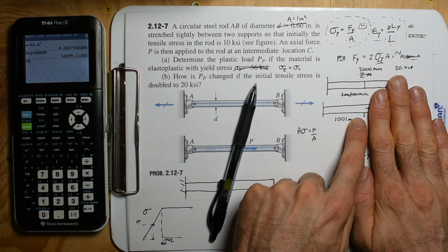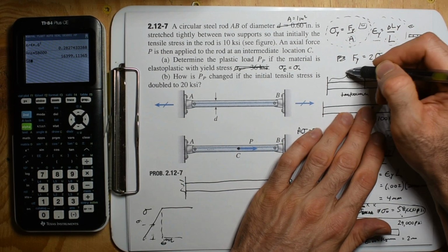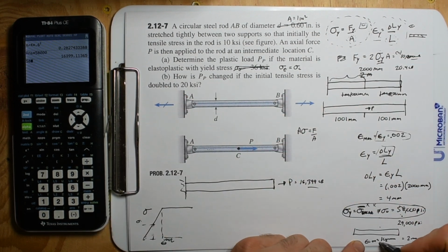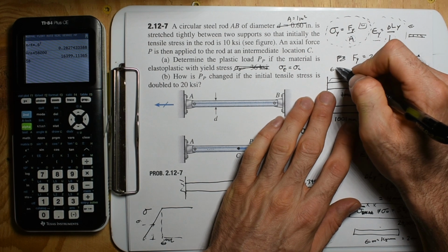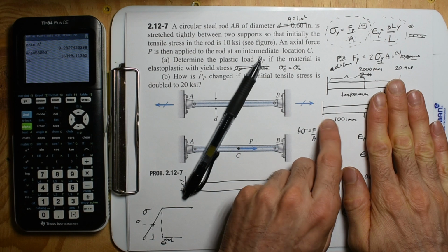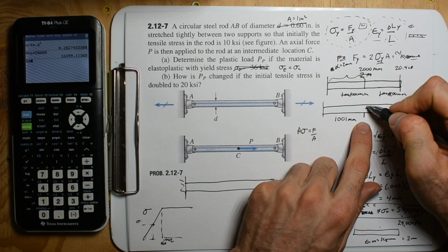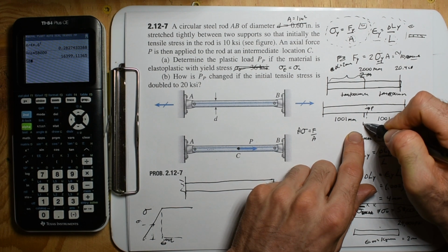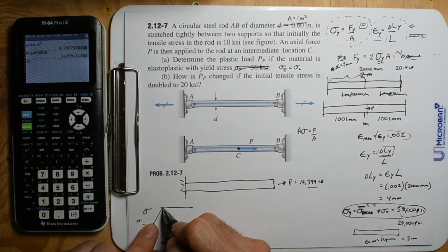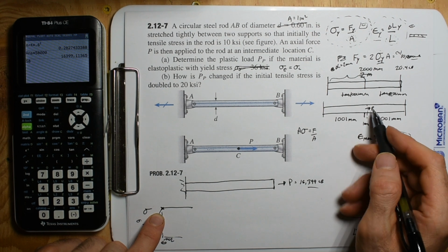This length, you have to go from its original length. So this bar right here was 1 meter or 1,000 millimeters. We know from the max strain or the yield strain of steel, this can only be a change in length of 2 millimeters. So when we cover this, it's already lengthened 1 millimeter. So the second we use a force and we lengthen this 1 more millimeter, this thing is shot. And I say shot as it hit that ceiling where you're just like, whoa, are people going to lose their lives? Well, not in this case.